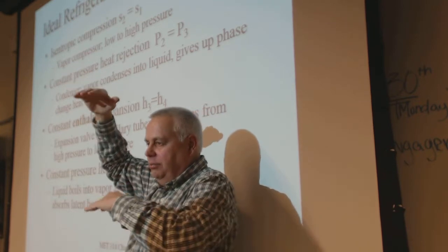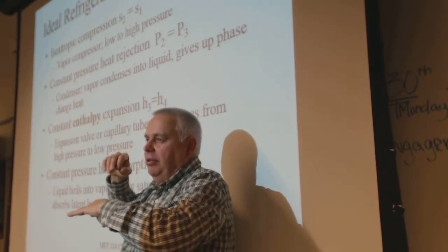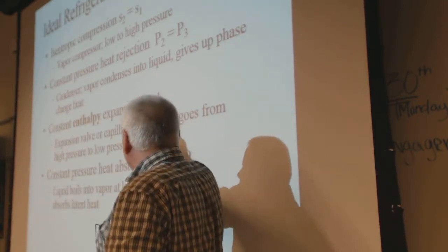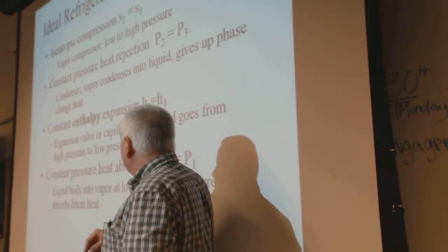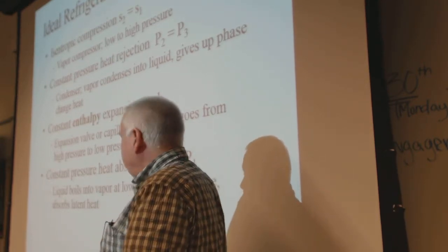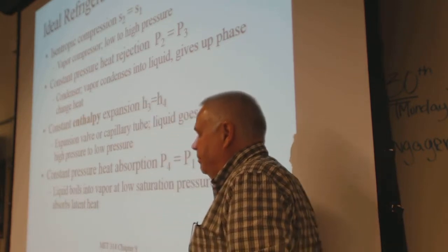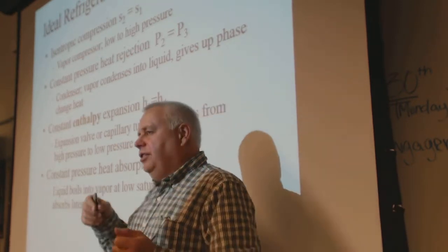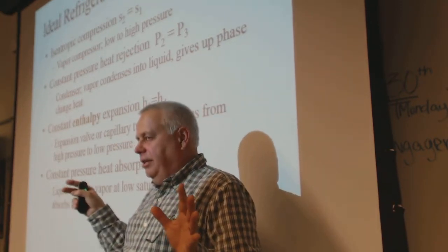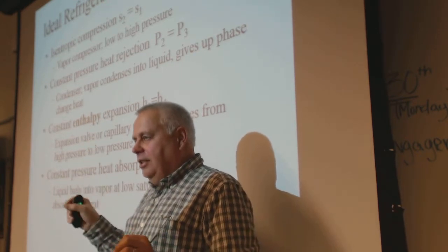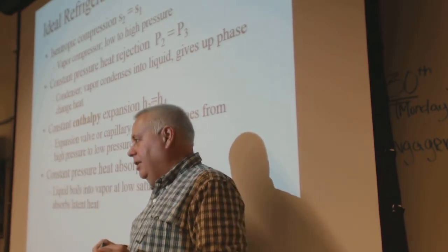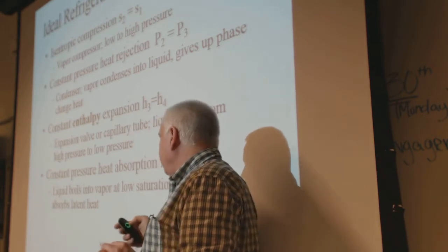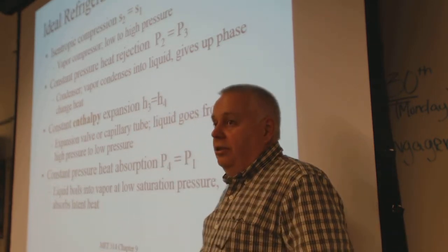There's a low pressure it's evaporating at. And between states 3 and 4, it's a constant enthalpy. That's the important part of the evaluation. Because it's phase change, we're not using any of those formulas that have exponents to the k, because that's about ideal gas, and it's definitely not ideal gas. So it's all about using the charts again.